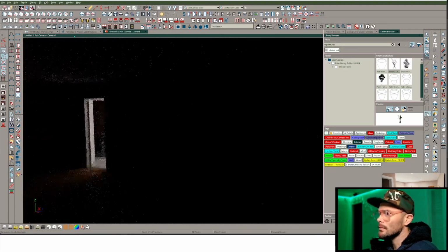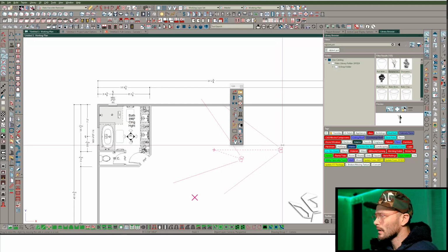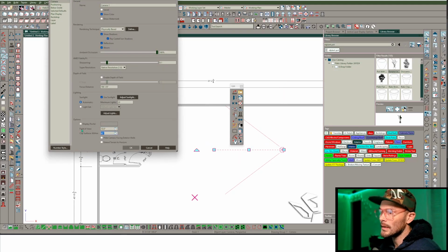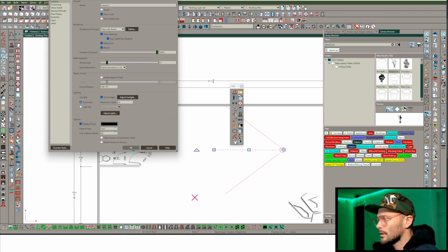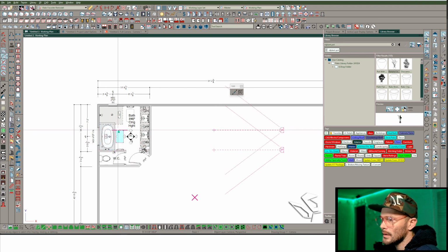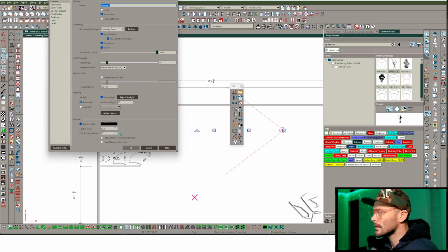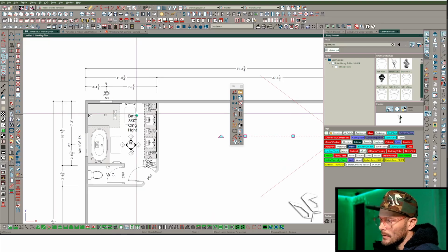Now let's do one that's really cool. So we're going to bring this way out here and see if we can find that camera. There it is. Let's open it up, set it to 10 degrees. Let's display poche. We're going to put black fill on poche. And then we're going to do a section cut on this. Let's figure out how this is aligned. I want to center this up maybe about right there. That looks good. Looks like the 10 degrees didn't follow. It did. Okay.